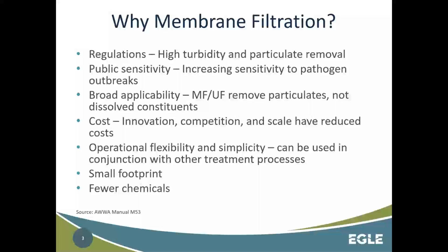Okay, so why membrane filtration versus our conventional filtration? Well, a number of years ago, with the surface water treatment rules getting more and more strict, the membrane filters became a dependable way with certain water qualities to meet the stringent turbidity and particulate removal requirements. With LT2, that's the regulation that's all about reducing crypto, there was a lot of membrane plants put in for that purpose. Not so much in Michigan, but nationally.